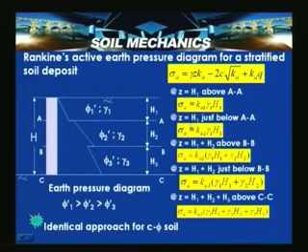Now the earth pressure ordinate just below AA, that means we want to get this point just below this. Just below AA the soil is at the same height, but the soil has the properties of phi 2 soil, which yields Ka2 is equal to 1 minus sin phi 2 by 1 plus sin phi 2. So sigma A is equal to Ka2 gamma 1 H1.